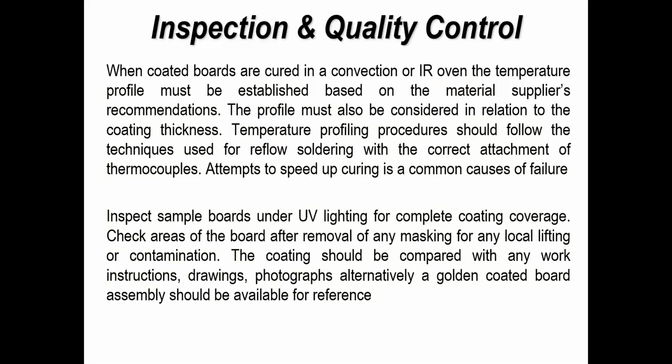If you're going to cure your materials on a board, rather than just allow them to naturally cure or in a box oven environment, if you've got an inline process, then you'll have to measure the temperature just like you do when you're reflowing solder paste. We do profiles, do the same thing.